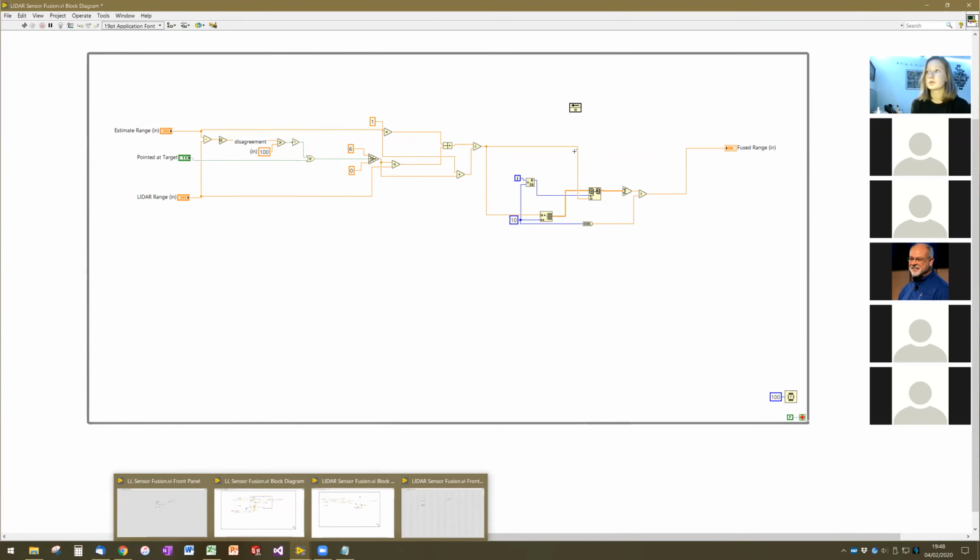I'm just going to stick it up here. It's going to be kind of ugly. This line that we kind of just threw in there, that actually is what we're using to initialize the feedback node. And then that gets plugged into, I'm sorry, this is kind of a nightmare of wires, so I apologize. And then the array with the newly replaced value goes back into the feedback node. And then this is the moving average.